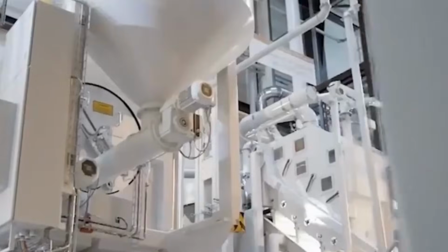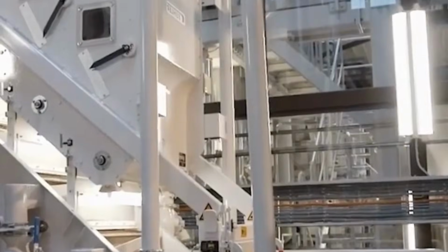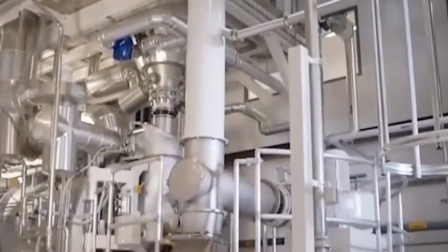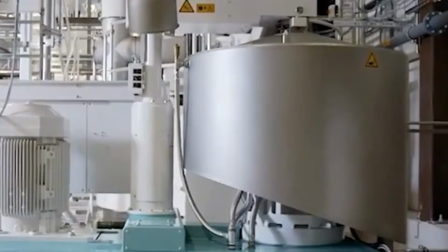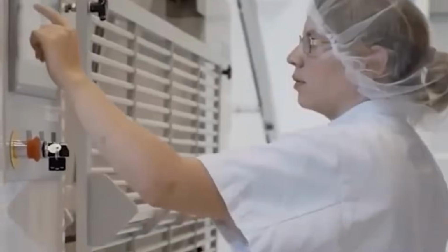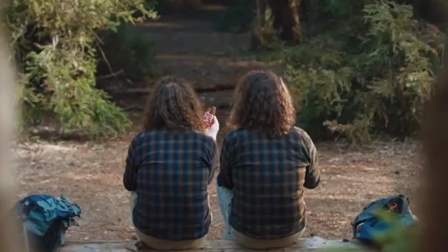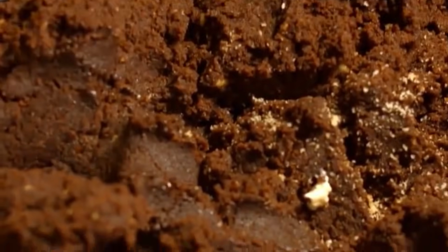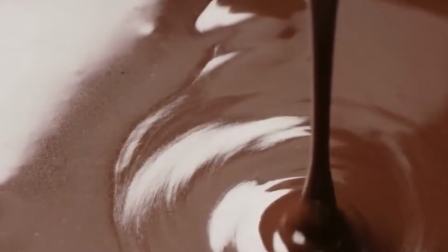Refined wheat flour, invert sugar syrup, vegetable shortening, powdered milk, salt, and leavening agents are dispensed into a horizontal planetary mixer. Dry ingredients are fed from bulk storage silos through gravity chutes or pneumatic lines, each portion controlled by weigh batches to an accuracy of plus or minus 1%. Liquid components are pumped from heated jacketed tanks and injected through metered valves.